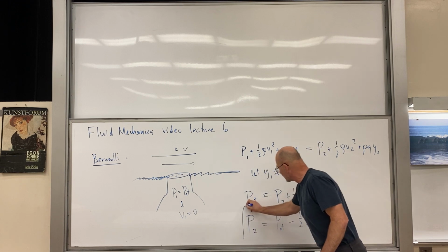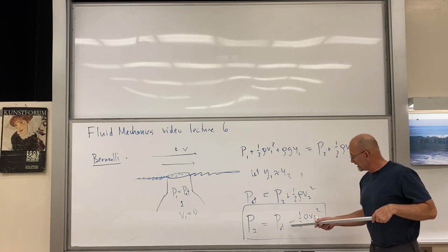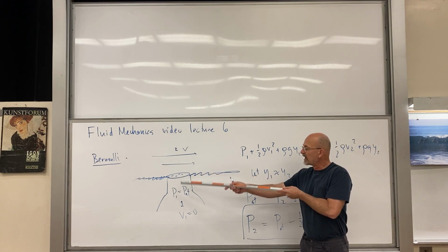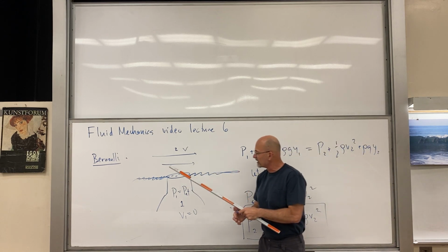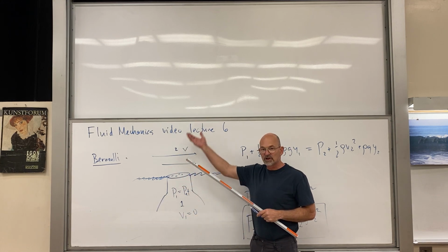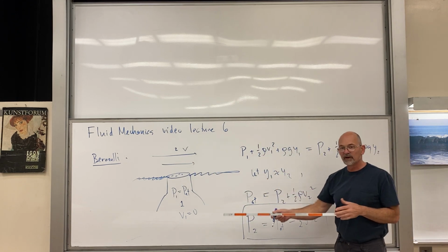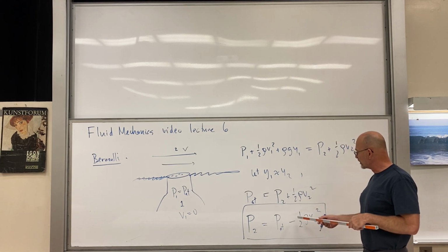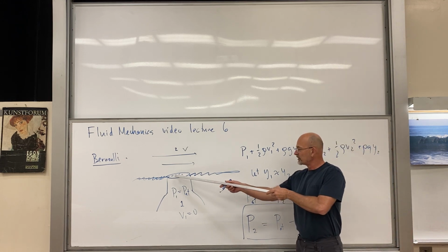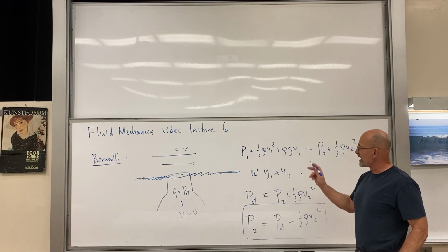So I'll put a box around here, kind of interesting. So first of all, you can see that the pressure is going to be decreasing. We're above here, higher pressure below, so with a high wind speed, we can actually imagine this cover just being blown up or knocked, launched vertically. And you could calculate the pressure difference times the area, which would give you the force. And those numbers would already show considerable force. So if you take this naively and you have say 1 square meter here, you're going to have a tremendous force pushing up. So that's the first application.